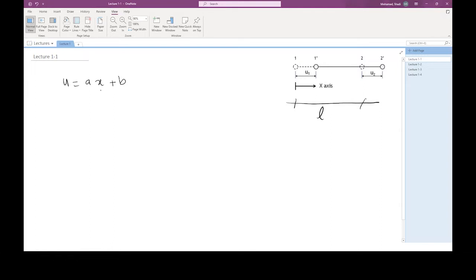And then I'm going to define this line based on the displacement at node 1 and at node 2. All right. So basically, I'm assuming that the displacement is going to be some U1. I'm just going to draw it here. So let us assume that this is U1. And then probably this is the element. And then you have probably another displacement U2 here. U2 is slightly larger. So you have U2 here.